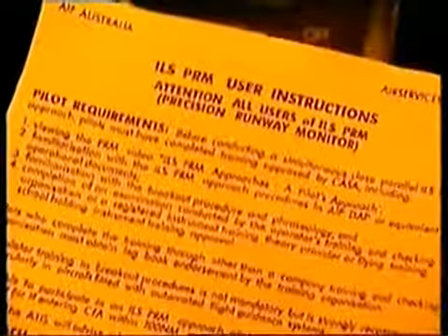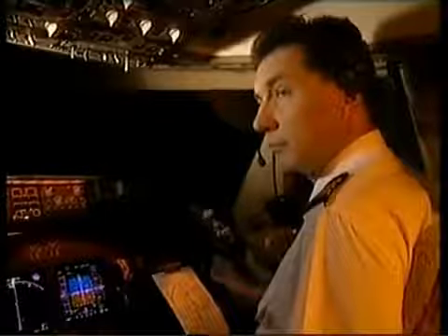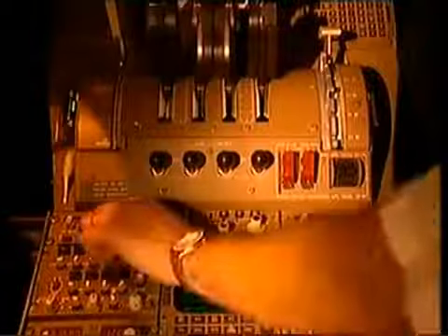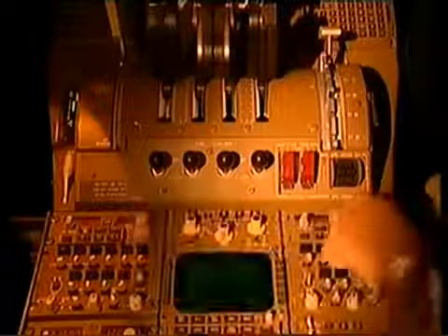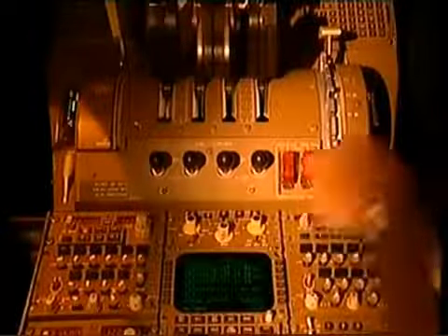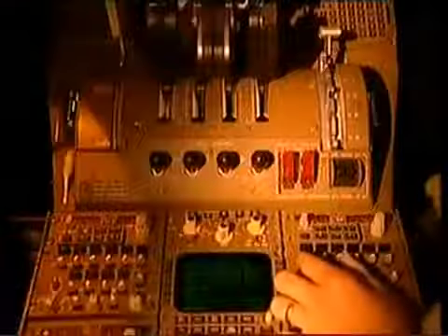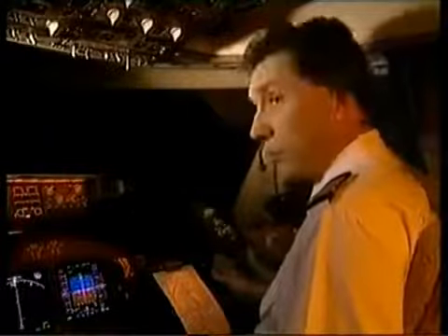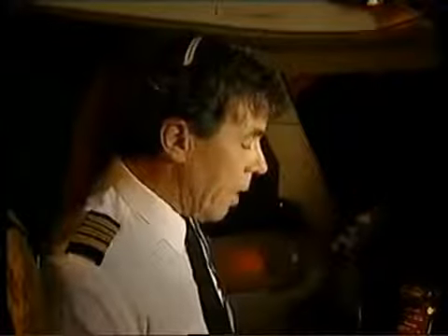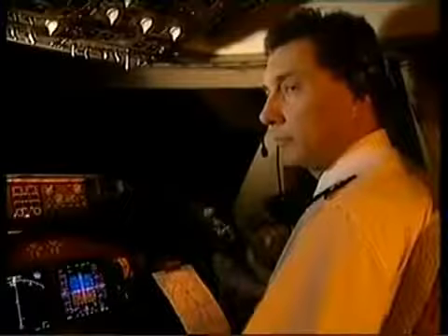Okay. The ILS PRM user page also specifies that the COM procedure is that when instructed by ATC to call the tower, we must have the tower on number 1 and the PRM frequency on number 2. We will only transmit on number 1 and we'll have to set the volumes about the same. So we just monitor the PRM frequency on the second VHF COM? Yes, that's just in case there is a breakout instruction which is blocked by a transmission on the tower frequency.